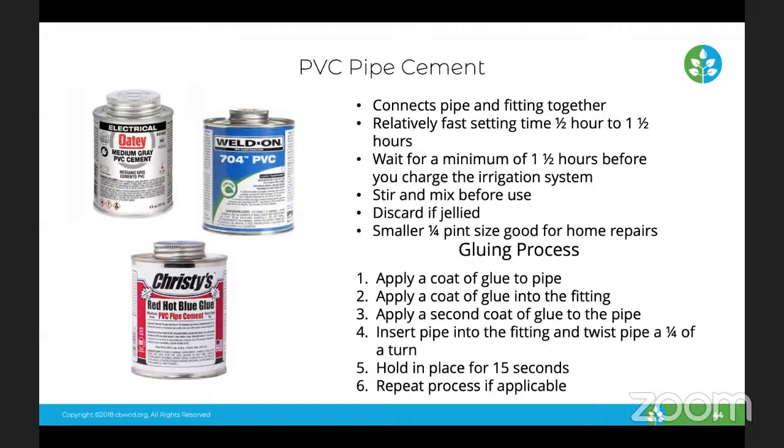I've had it where I've glued something, got really eager, needed to go somewhere, turned the system on, and guess what? It popped out, and now I had to redo it and then wait even longer. So always the best option is to wait as long as you can. Again, that's why making repairs, if you have large repairs, or if you want to add sprinklers or do any kind of major renovations during the fall and winter when we don't need the system to run as frequently, is a good idea.